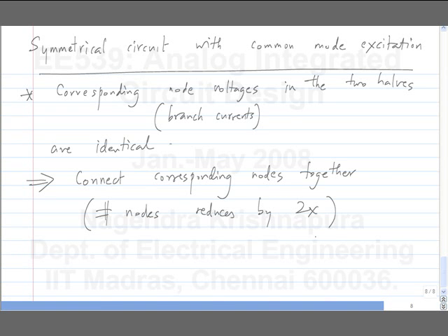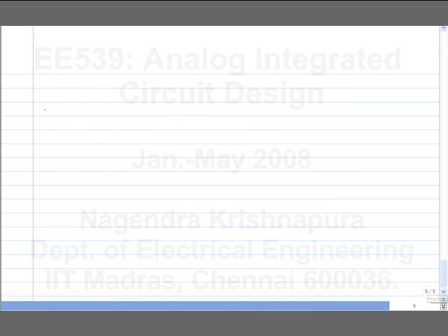So we can work out the example. We already have a sample differential circuit. I will make it, and the exact symmetry in the circuit is very important. If you have identical transistors here, but different loads, this is not true. It's only true for exactly identical circuits.